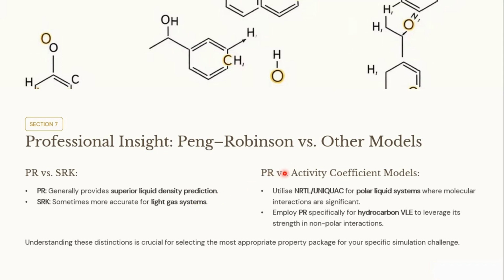When we talk about Peng-Robinson versus activity coefficient models, Peng-Robinson belongs to equations of state; utilize NRTL or UNIQUAC, which belong to activity coefficient models, for polar systems where molecular interactions are significant. Employ Peng-Robinson specifically for hydrocarbon VLE to leverage its strength in non-polar interactions. So you must have a clear understanding of which property package to use when.